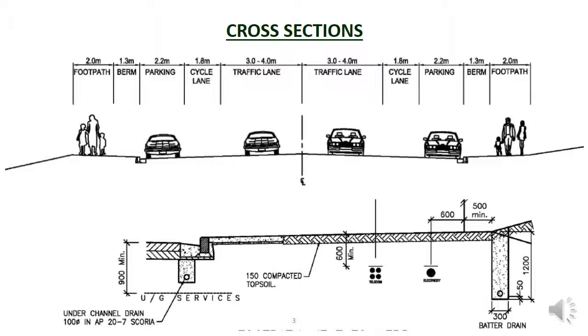These drawing extracts are from Chapter 7 of the Auckland Transport Code of Practice. You can see it provides good guidance on the widths of the various parts of the road. The road we are looking at has similar dimensions, but they altered some of the widths to match the road location. For example, our sample road does not have parking as there are no houses accessing that part of the road, and there is no room for the berm, so the footpath is next to the curb.